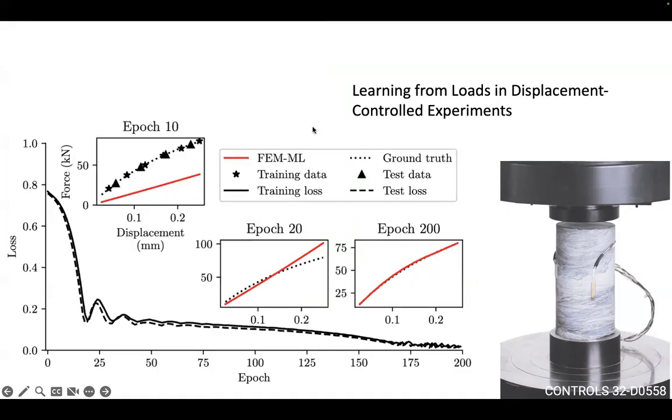And this allows you, for instance in this example, to use just 6 values of force to completely train a constitutive model. Here you have the force displacement in output from our FEM solver after 10 training loops, and it's obviously off. The dotted line is the ground truth, imagine your real experimental data set. During training, we change the parameters of the constitutive model until the FEM solver returns the correct force displacement curve. In this case, a material softening curve, so a rock with a softening law. And this is done with just 6 scalar values of forces.